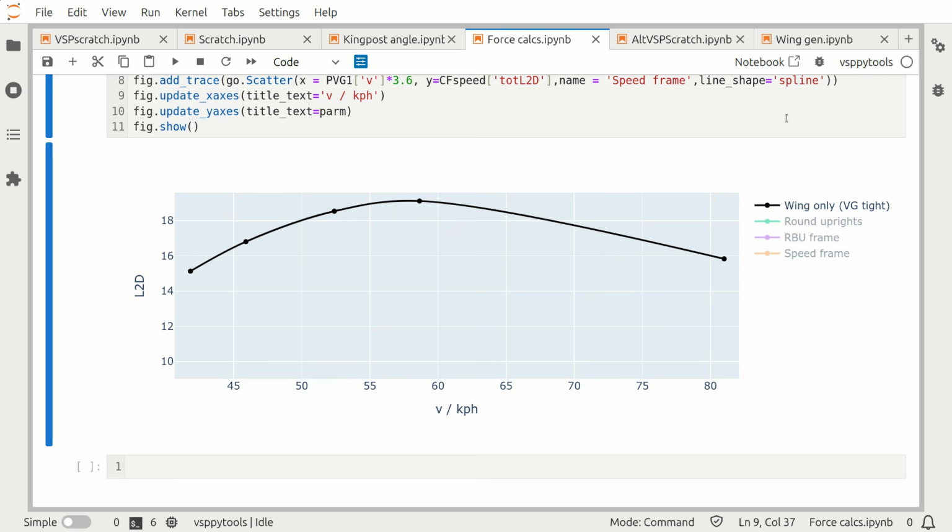So I've plotted some of this data then. So I'm using the data from the vortex lattice analysis of the Puma wing. So this was using some actual scan data for the shape of the wing, modelling in OpenVSP and getting some results out of it. So if we look at the lift to drag ratio as a function of speed, I mean you can see it's unrealistically, or it seems unrealistically high for a hang glider. You've got a glide angle there of 19:1, which I bet we'd all love, but of course this is just the wing. This is without any pilot, control frame or wires.